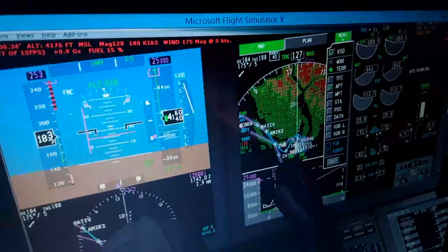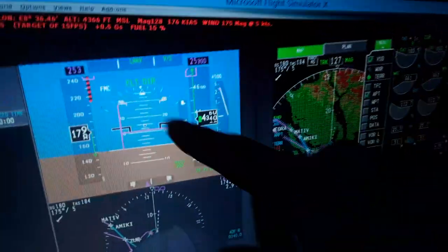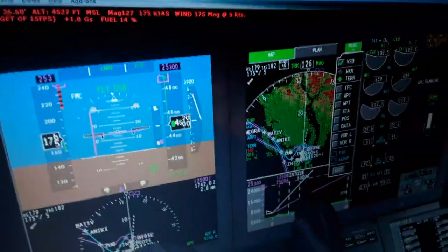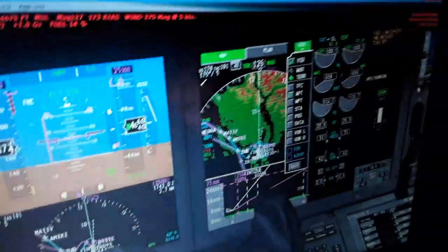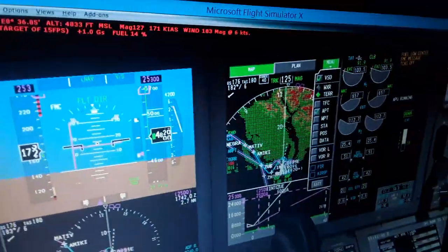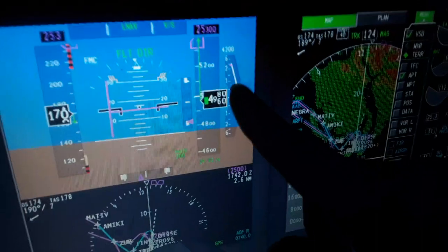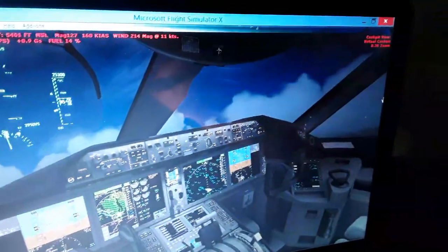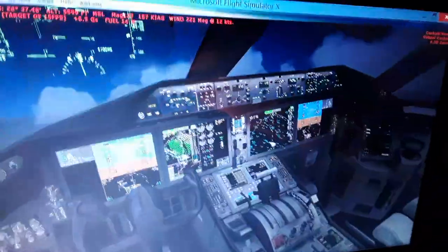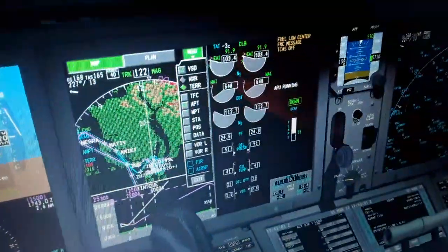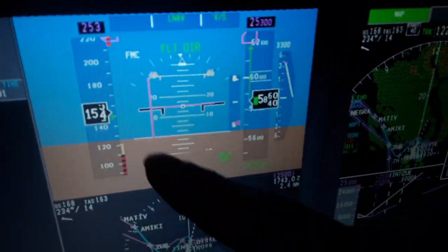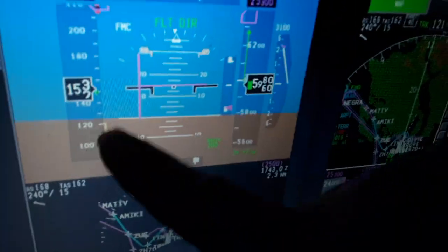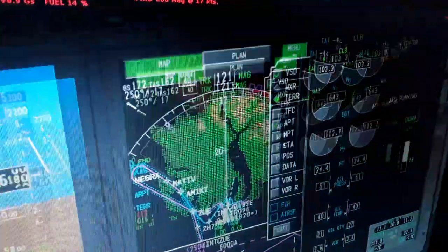The airspeed 180 knots, decrease because we have high pitch attitude. Also the stall speed here, the wind direction and speed, also the flaps limit over here. We climb with 4,200 feet per minute. You can see we keep climbing. So we have the data here. You can see again the airspeed, the stall speed we're gonna reach is 120 knots. We're gonna stall the aircraft, so we need to pitch down the aircraft and also increase the thrust levers.